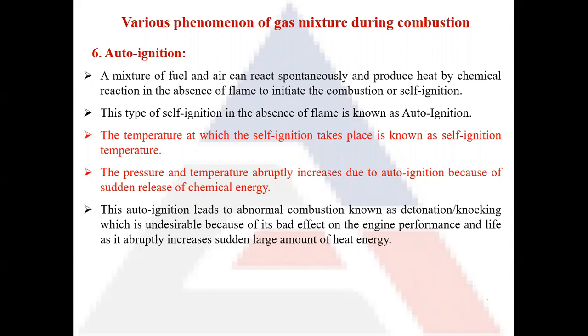inside the IC engine. So in the absence of any flame or spark, the spark has not been ignited, and because of the compression process, the heat inside the combustion chamber reaches the self ignition temperature, and various flame fronts are formed. These various flame fronts start to ignite, and when they collide with each other, they result in knocking or detonation.